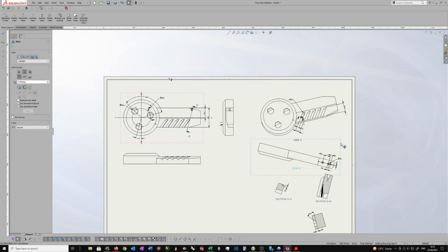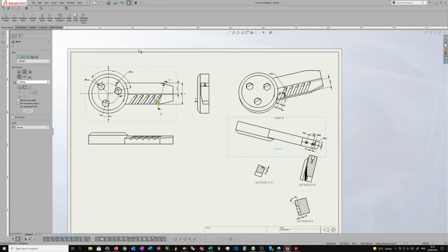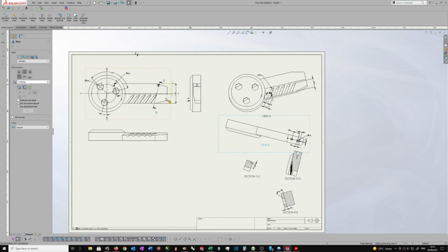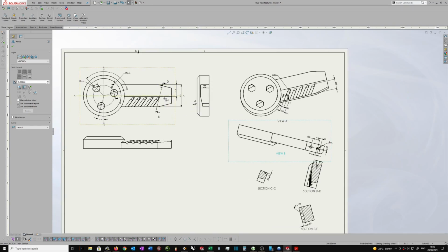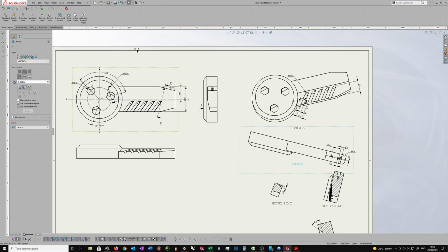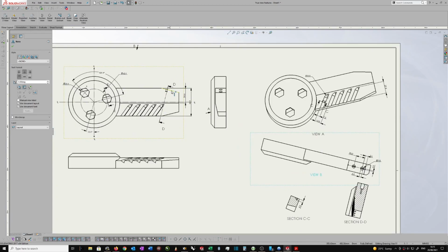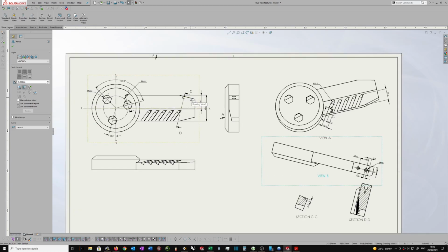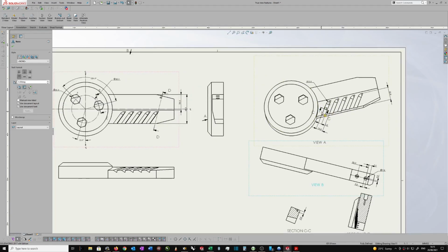So that's that done for now, and so that should give you a good idea of how to do this kind of dimensioning. I'm not going to dimension the rest of it, but it's very important to keep in mind that any feature which is not true to you, in other words, if you look at a view, so that plane there, I can't see what's going on in any of the 3 standard views. If that's the case, you need to get it on an auxiliary view, and you need to do your section view in the auxiliary view. In this case, because I'm flat on, it's okay to do it like that.